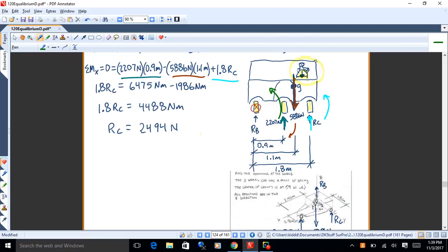So when you make a 3D problem 2D, the line of axis that you're looking down will be the moment you take it about. Yeah, right, because that's the definition of a 3D moment: the axis of a 3D moment vector is the axis that you're rotating about. So if you look down the x-axis, it's the x moment, right? Okay.